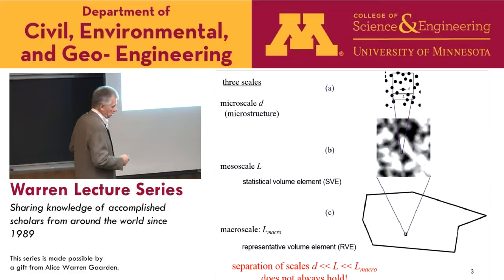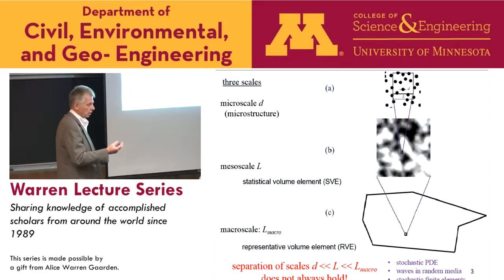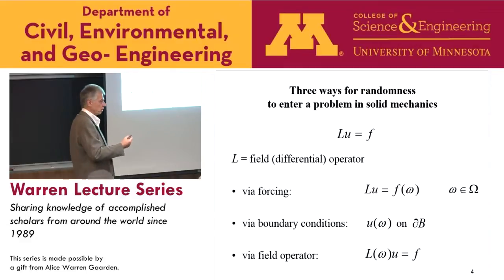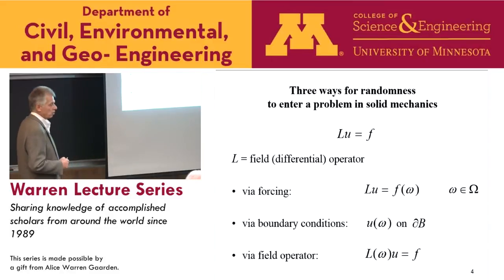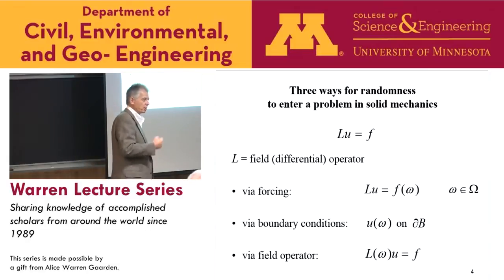And a classical problem in stochastic mechanics is to ask what's the difference between doing a homogeneous medium problem and getting this one solution, versus a random medium problem, which means getting a distribution of solutions and then taking the average, the ensemble average. How different is the average from the solution of the problem which is homogenized right away, a priori? So this is what all stochastic mechanics people want to do, and always they want to arrive at a result. You see, if you homogenize too early, you're wrong.